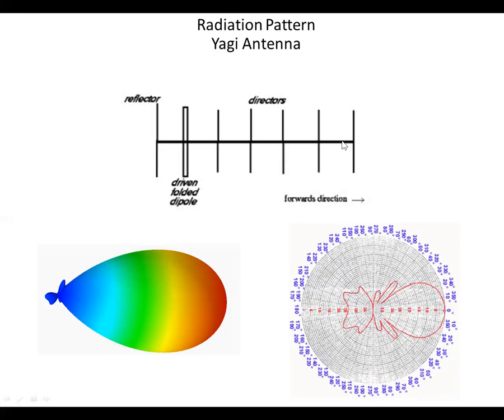If you had more elements on this antenna, you could concentrate the power in even a narrower angle, so you get more power going out, which should get you farther distance. But there again, it's a trade-off. You need more elements to get a higher gain and tighter propagation lobe.